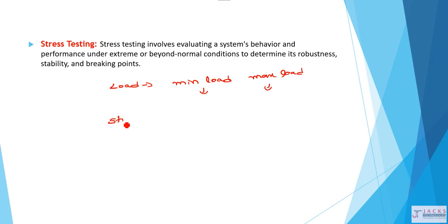Now in stress testing, what do we do? Here we are applying 0 to 5 messages. Here applying 4464 messages. Now in stress testing, we will apply 5500 messages. We will send 5500 messages over the CAN. Now we see the same. Is there any time delays or is it raising any errors? Okay. Now this is the minimum stress you are applying.